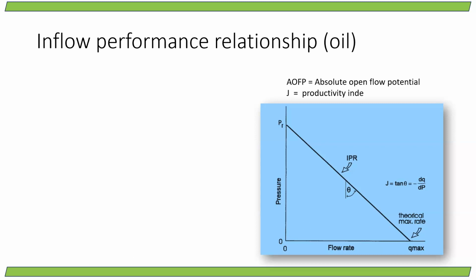In the same reservoir, you have different IPRs. Every well will have a different IPR. They are all unique. Probably the size of tubing of one well could not be suitable for another well. So maybe the production could be different. If you provide an instruction with tubing size, choke size, or whatever adjustments you have done in this well, it could not be suitable for the other well in the same reservoir, because of a number of constraints that we may come across through the reservoir.